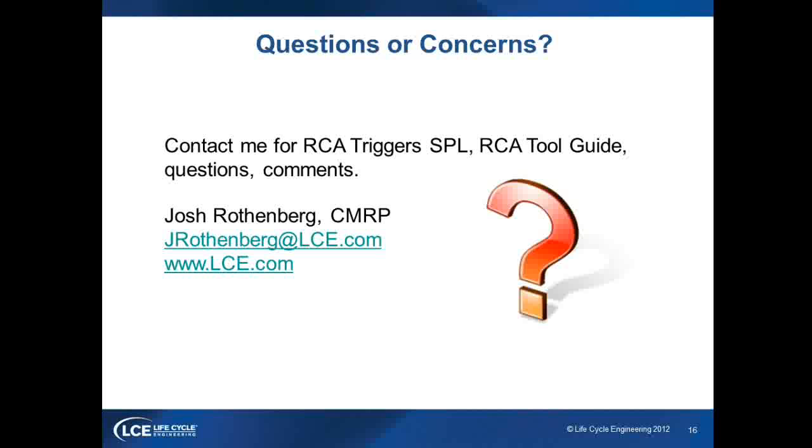But in terms of how you perform the analysis, who should be involved, those types of things, that's pretty standard throughout. You want a trained reliability engineer leading the analysis. You want a cross-functional team of operators, mechanics, technical people, subject matter experts, etc., involved in the RCA process. You want to have action plans and A3 reporting. You want to have visual management in place to understand where you've been and where you're going. You want to be able to effectively manage your action items to make sure that they're getting addressed. All those things will be identical regardless of the industry that you're in.